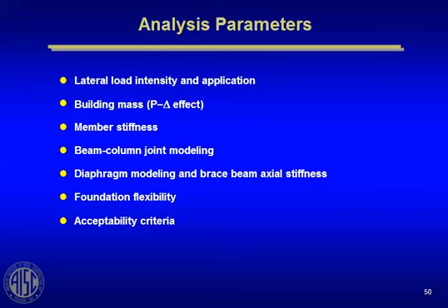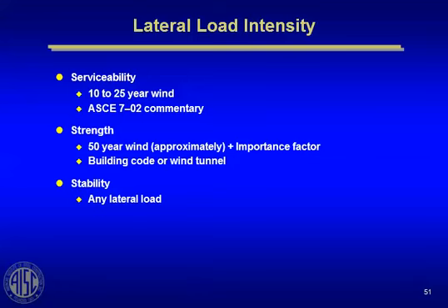We also have to say, okay, for all of these serviceability limit states, strength limit states, and stability limit states, what's the acceptance criteria? What's my fail, pass, fail, go, no-go requirement? We're going to talk about that. Okay, serviceability means usually drift or perception to motion. For drift, different engineers do different things when they check drift. Some engineers use the nominal code load, which is usually the 50-year mean recurrence interval windstorm, or for an important building with an I factor of 1.15, it's a 100-year storm.